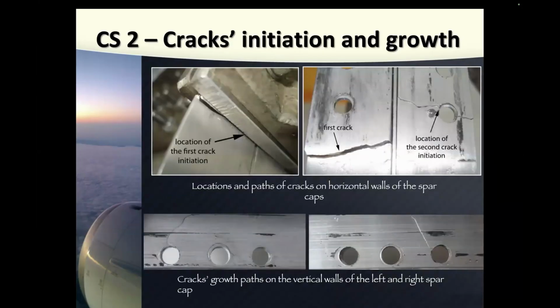And then this is what we got. In fact, we got 2 cracks. One on the left cap and one on the right cap. So the first crack started somewhere in this area because we couldn't see. Later we analyzed that. Of course, we didn't analyze only one spar, we made 10.